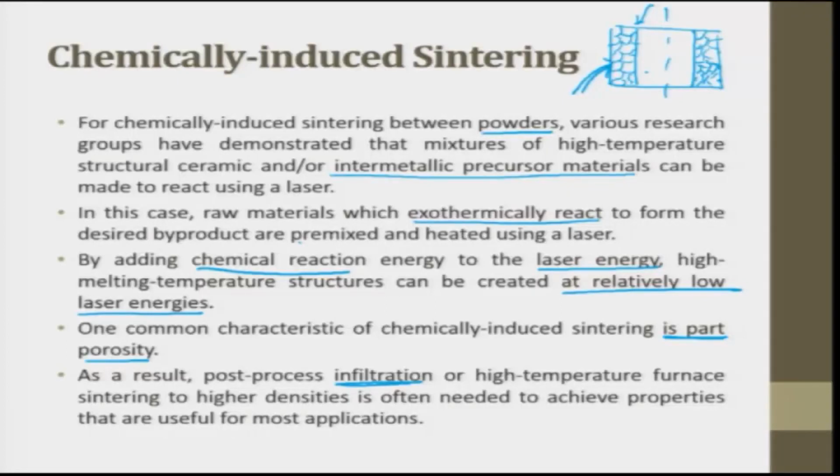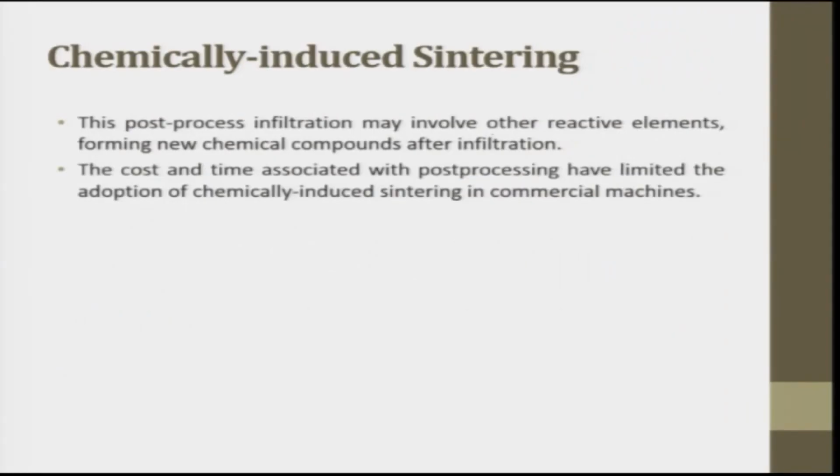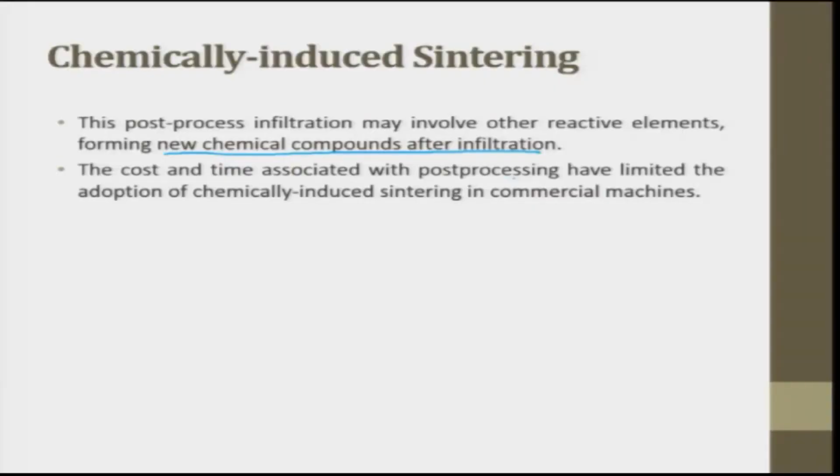Okay, so we use pores for our advantage. We use pores for our application. We choose the pores for our applications. This post-processing infiltration may involve other reactive elements forming a new chemical compound after the infiltration. What I was talking about is, under very high pressure, the infiltration pushes the liquid inside the pores. At some point, this liquid can also react with the base material and form one more compound or another reactive product which can be used for our benefit.